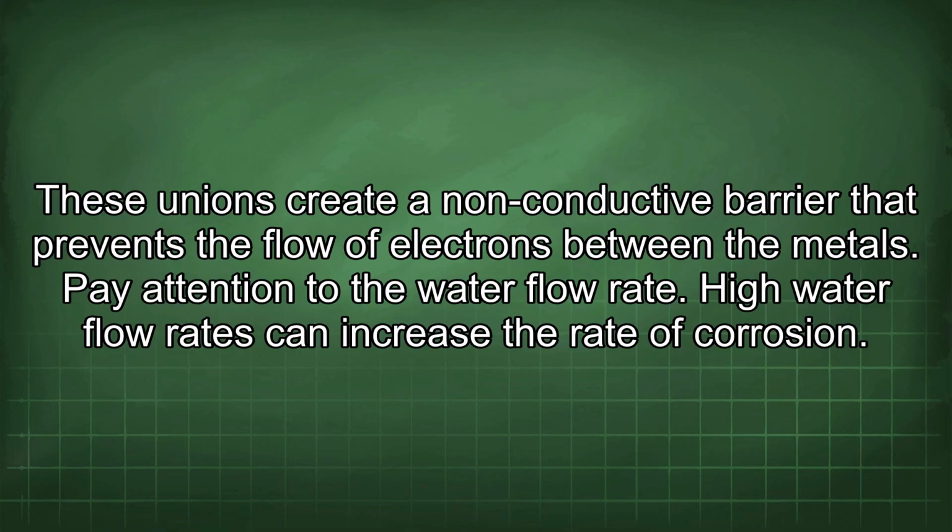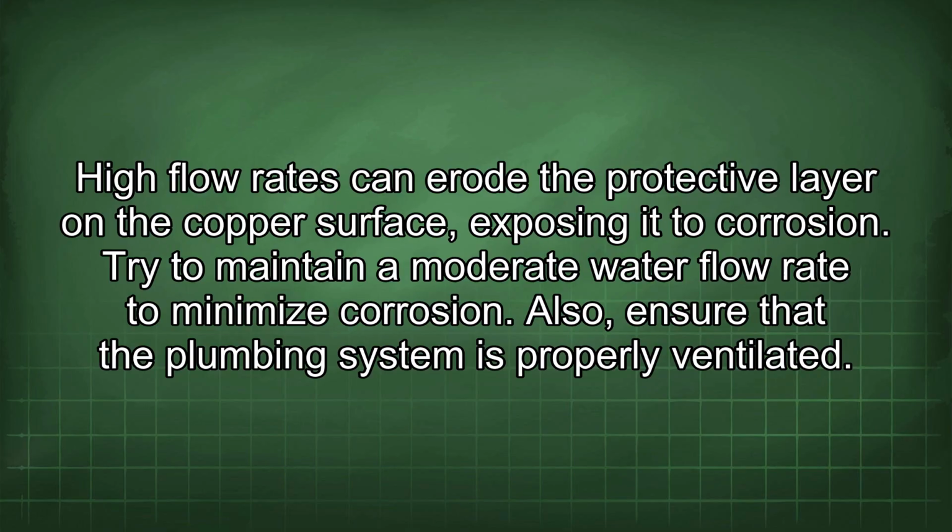Pay attention to the water flow rate. High water flow rates can increase the rate of corrosion. High flow rates can erode the protective layer on the copper surface, exposing it to corrosion. Try to maintain a moderate water flow rate to minimize corrosion.